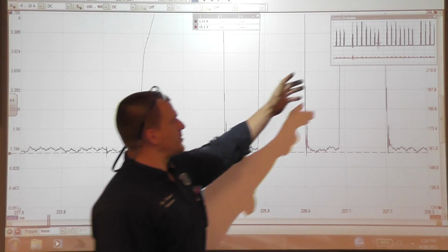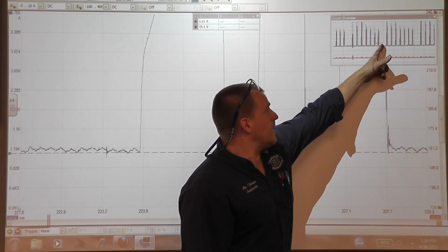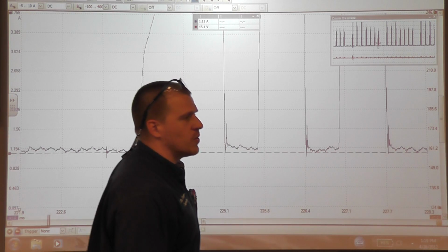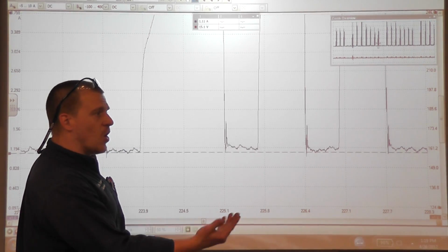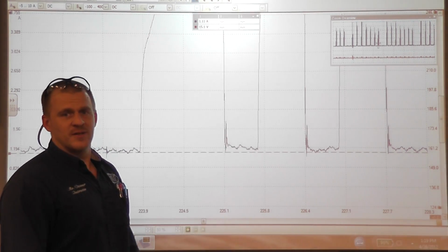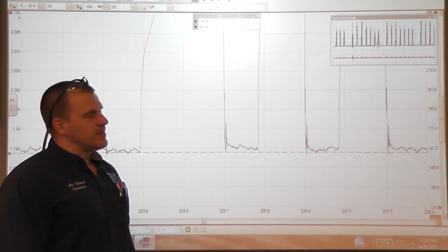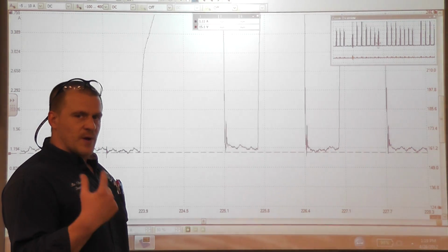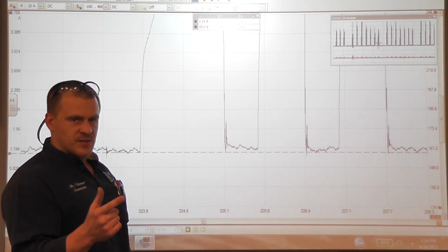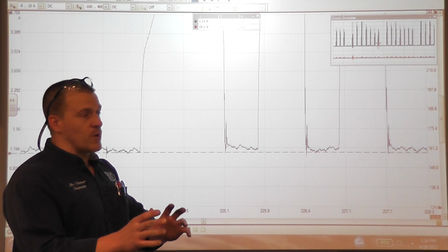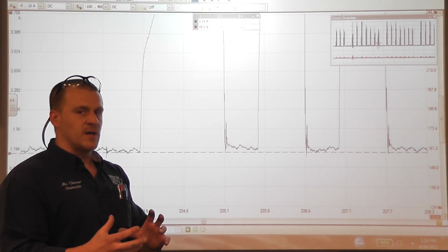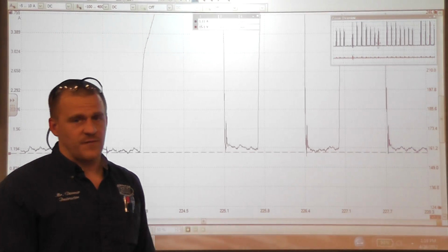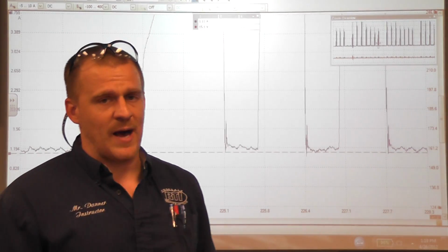So not only do we have an issue with cylinder 6, which is the empty spot here, the one right before cylinder 6, that should be cylinder number 2 in the firing order, also has a coil issue. Got some major problems here. I think the next step is going to be, let's address that coil number 6 and get a current ramp pattern of that one to see if it's really, really high, and that'll tell me whether or not that cooked this driver. Now sometimes drivers can fail without over amperage, so we'll see what happens.